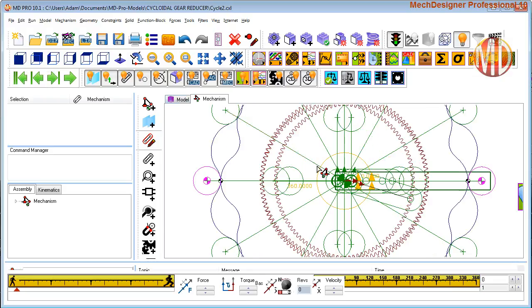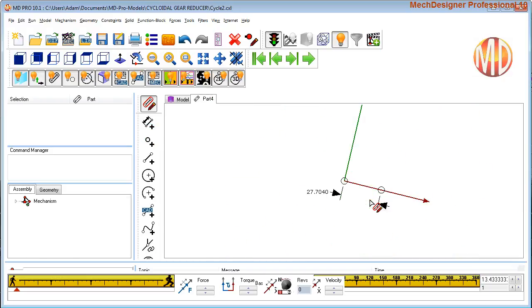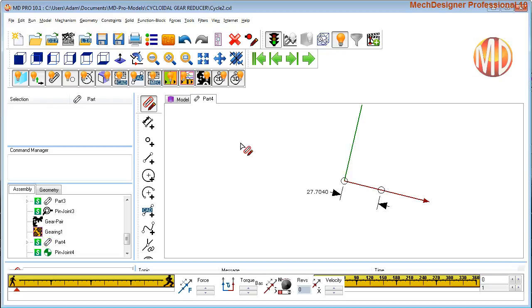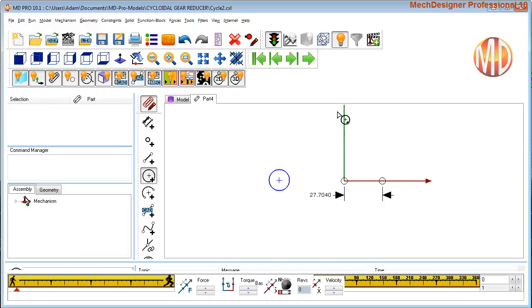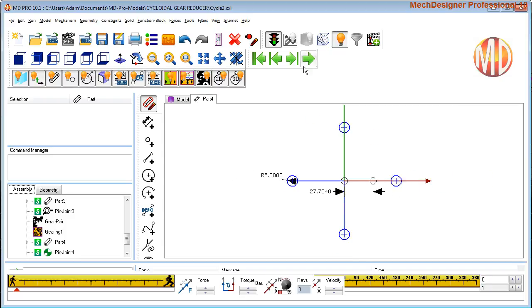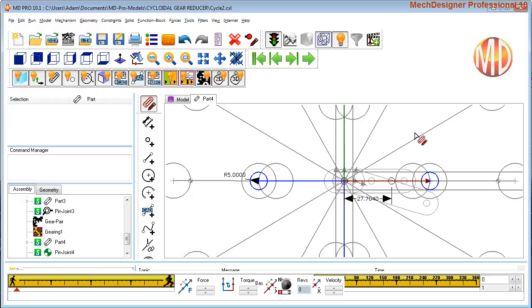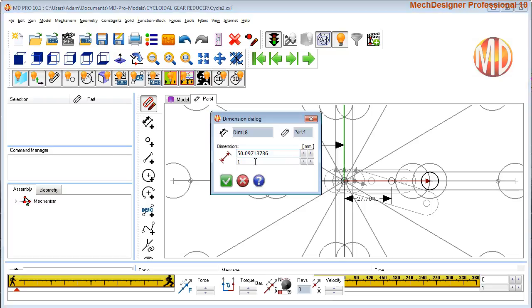So what we need to do is edit the output rotor, which is this part here, and I'll just send this to home, and then I'll put in 4 pins to remind me what radius I need. I'm just going to show the other sketches, and I'll just dimension one, and these have to be in the middle of those two other circles.